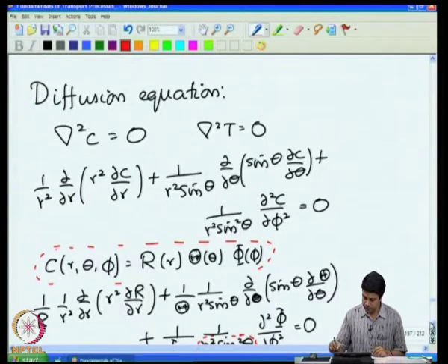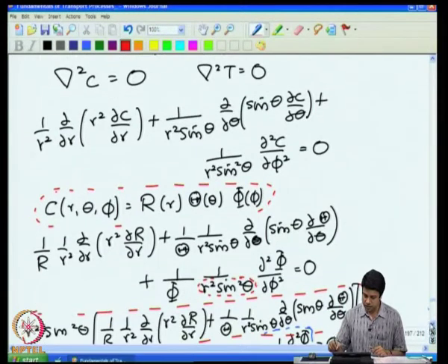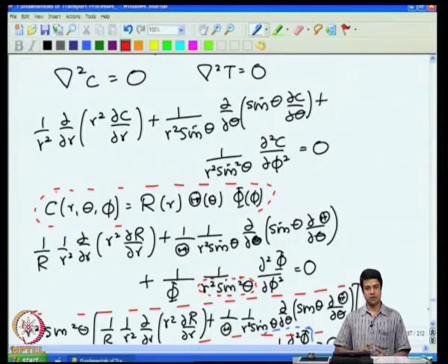I was solving for you the diffusion equation in a spherical coordinate system. Procedure is exactly the same in any coordinate system. Whenever we have a function of multiple coordinates, if we can do a similarity transform based upon the scaling of the coordinates and the boundary conditions, that is best, because we can get a solution in terms of just one similarity variable.